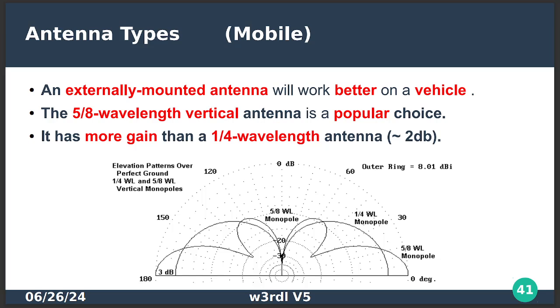I think the one with the 4 lobes is the 5/8 because it's actually reaching out farther, and the 2 lobes is the quarter wavelength. The reason you would get those 2 extra lobes near the top with the 5/8 is because you're not far enough off the ground to let it flatten out. But the quarter wavelength is still not reaching as far, even though you've got it concentrated into just the 2 lobes.